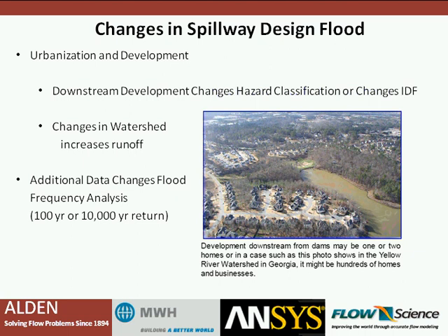So what this does is actually change the design requirements for the dam. And rather than be in what might have been considered a low hazard category previously, it would now fall into what's considered a high hazard category, meaning that the spillway would have to pass a lot more water. Otherwise, failure of the dam could certainly result in the loss of life.